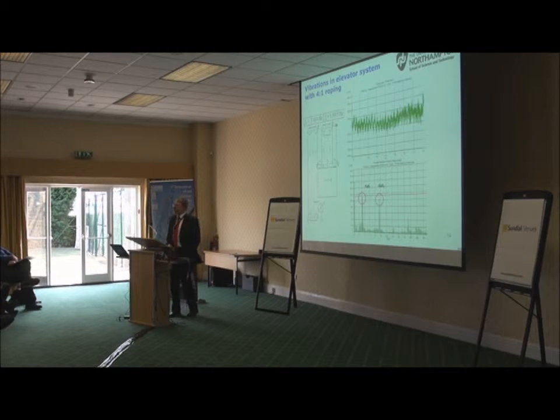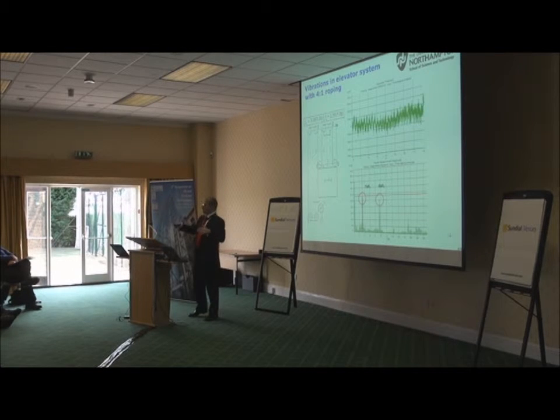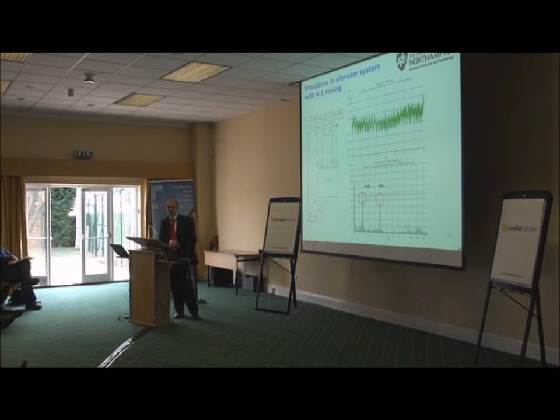We look again at the bigger picture. We look at how this system behaves in terms of frequency. We run the car, and we take the measurement while the car is, let's say, vibrating at a specific level. In this case, it was the bottom level loaded. This is the signal which I showed you earlier on, quite polluted. You cannot see frequency. You do have an FFT here on this signal, and you have frequency peaks.